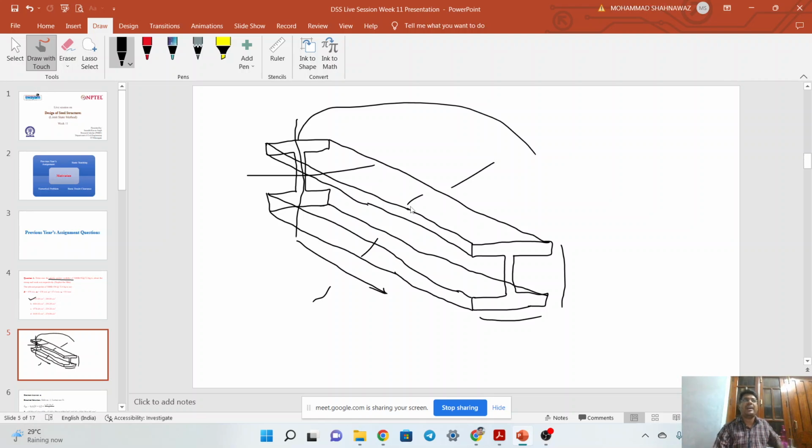The same case happens in the case of a pipe having a circular cross section. When you fix its circular dimensions, meaning the area of the cross section of the pipe, and now start increasing its length, after one time it will start acting like a wire. A wire, because of its self weight, will sag. The same thing will happen in this also. So that is why we don't want our member to be like that.